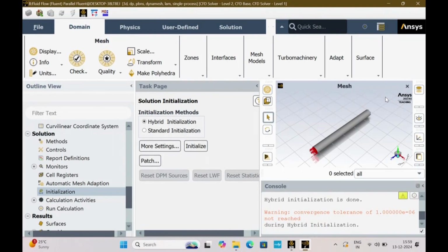So click on dynamic mesh, tick on that box, select create or edit, choose wall from the drop down menu and click on system coupling. So that part was only different from yesterday's simulation, rest all are same.